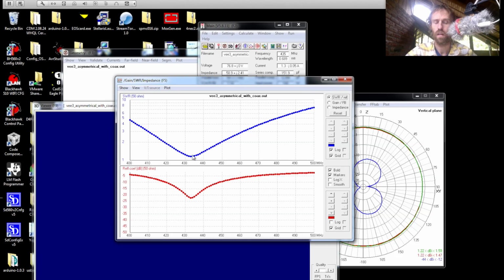So what this means is with the V and the moxon, if you're going to use them, they're simpler designs in a lot of ways. The moxon is a good directional antenna, but you need to be quite precise with your measurements with these two antennas. If you've got elements slightly longer or a slight angle off or anything like that, they're going to deviate from this center frequency, and then they'll come out of tune a bit more rapidly.